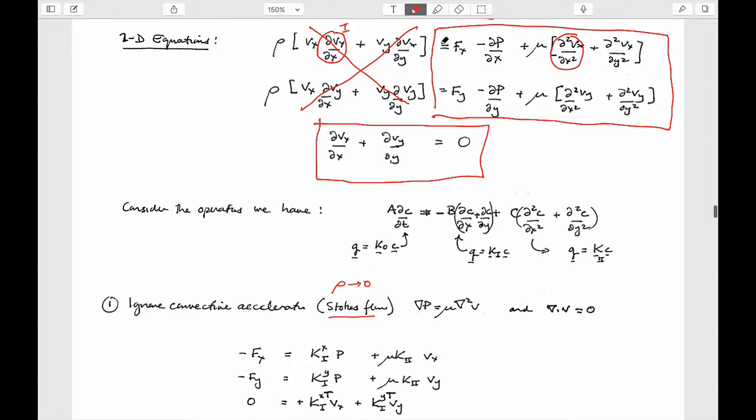So what we could do is rewrite these 3 equations. I guess I should leave both sets of equations on. So this one here is here. We have a force, which I've taken over here. We have a first order term operating on pressure, which I've written here. The Roman 1 means it's first order, and this is our conductance matrix. So this is the FEM statement, FE statement.